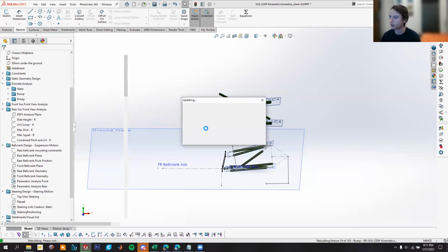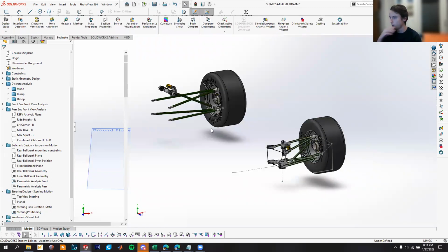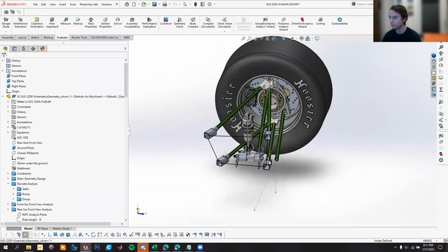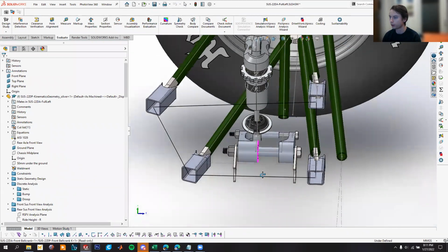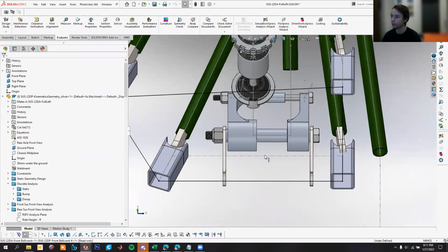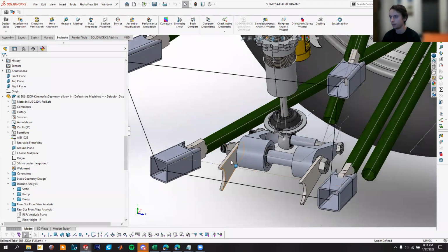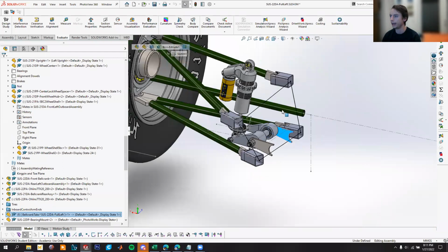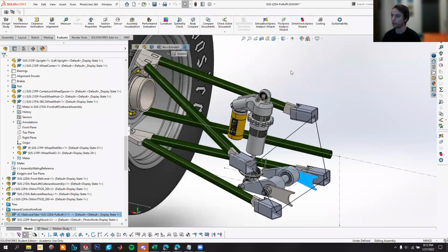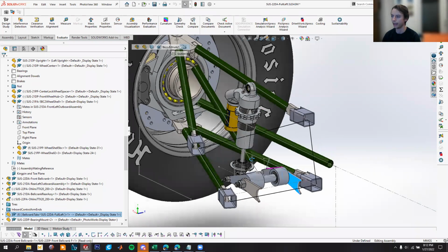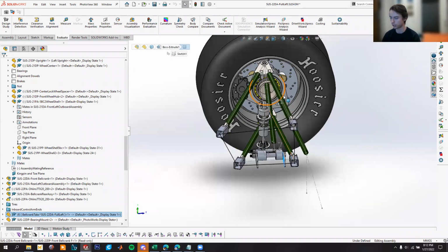In the suspension, there are not a lot of 3D printed components. We might have some 3D printed jigs to help position things. I know Jack Watson is currently working on a little 3D printed jig to help position these front bell crank tabs and the damper tab, which is yet to be designed, but it's just two simple pieces of steel which get welded onto the chassis. But the jig is to position these tabs and the damper tab relative to each other and relative to the rest of the suspension.